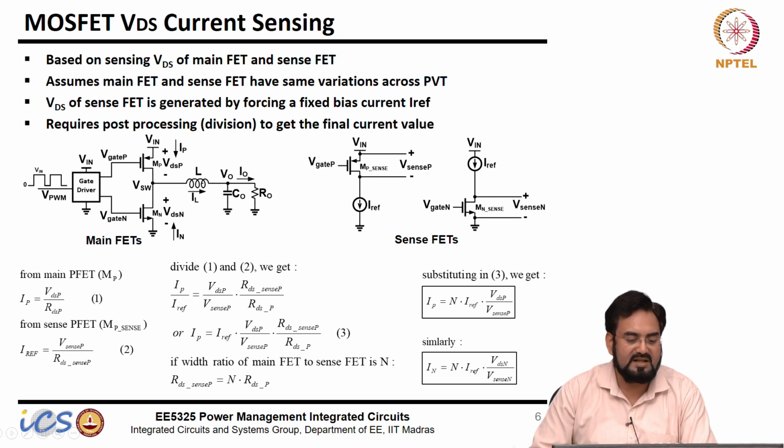So when you are turning on, this is connected to ground or not ground basic. If it's any other voltage, then that will appear here. So it's better to have the same voltage here. And Vin is also the same. So we are turning on. Both are operating in linear basically when they are turned on. And this guy will carry I load current, and this guy will carry IREF current, which is fixed.